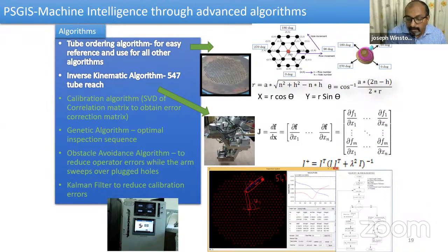Since it is a 2-axis arm, it comes as a 2x2 matrix. So inversion is much easier, because you can directly interchange the diagonal elements, change the sign of the off-diagonal elements, and do the inverse. Otherwise, computationally, it becomes more trouble for the motion controller to do the iterative process and get into bigger numerical troubles during the actual case. So that is why we often do this.